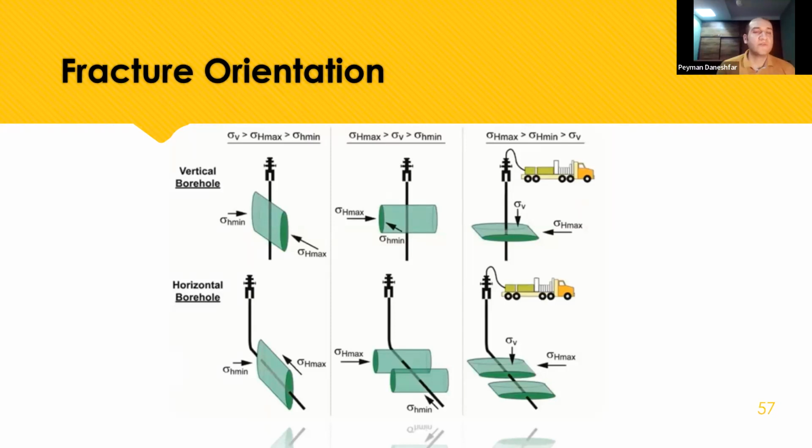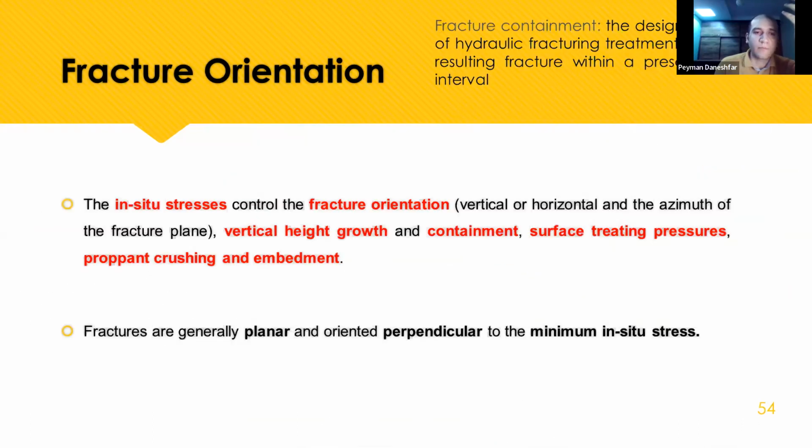Please check it for yourself, because all the time you should repeat this sentence for yourself: a fracture is generally planar and oriented perpendicular to the minimum in-situ stress, but parallel with the maximum or vertical stress.